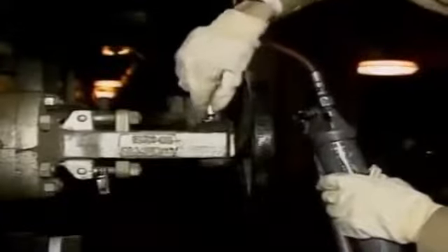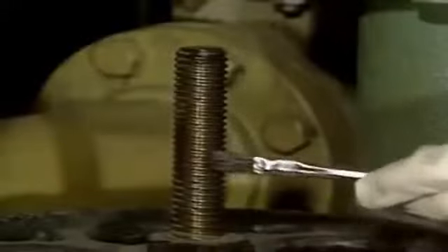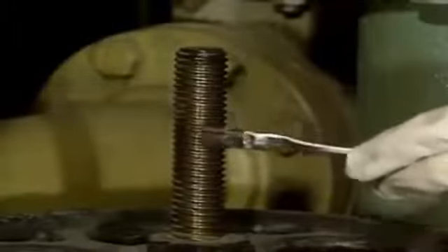Besides locating and identifying leaks, another task that an operator may have to perform is valve lubrication. Valves need lubrication to prevent components from wearing during operation. Each type of valve may require a different type of lubricant or method to apply the lubricant. For example, some valves have grease fittings and require the use of a grease gun to lubricate them, while other valves may have the lubricant applied directly to a component, such as this valve stem. Because there are so many different methods that may be used to apply lubricant, you should always check your company's procedures before lubricating a valve.